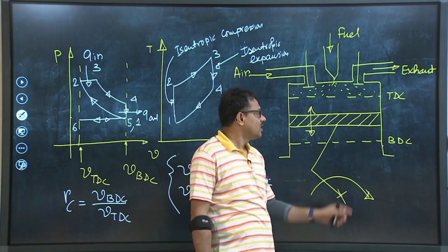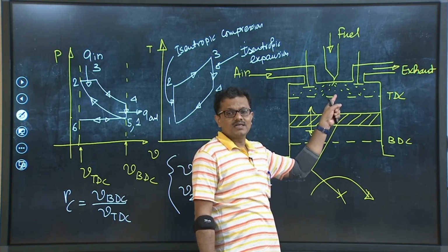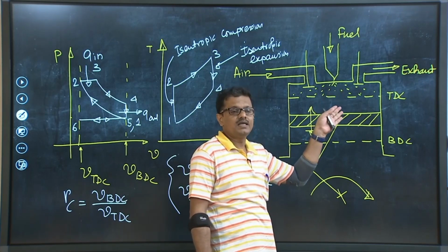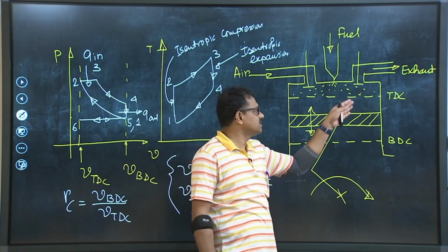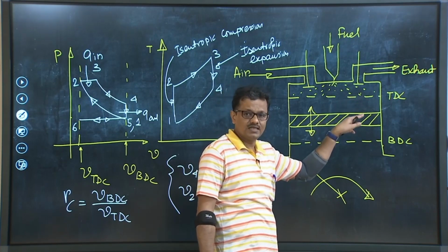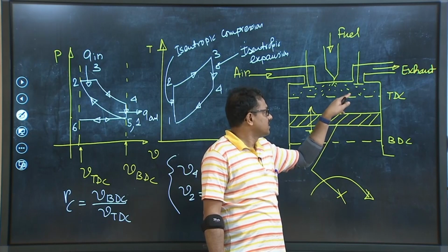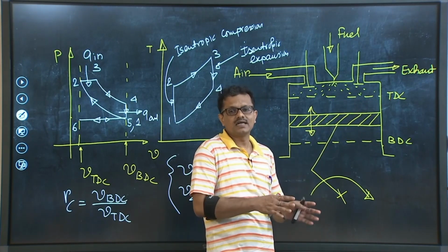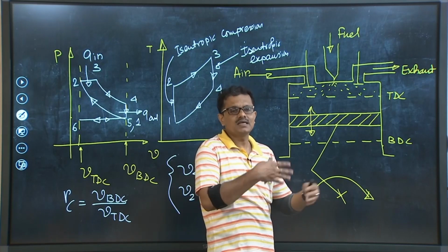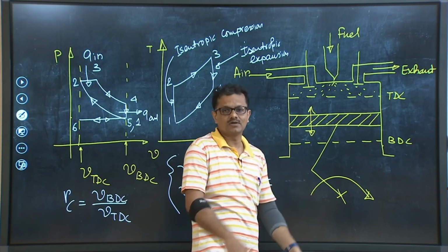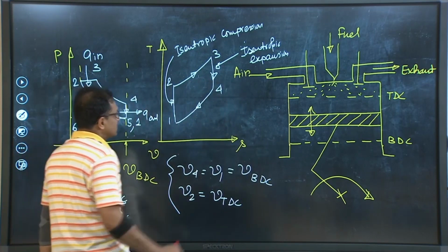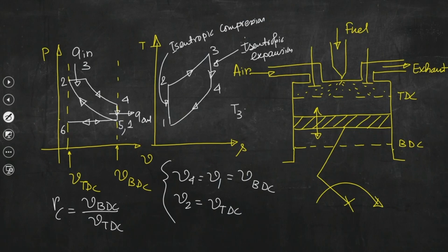and this is a very good assumption that I can tell you, because there will be a rise in pressure during the first phase of combustion, and that pressure perhaps will be reduced as the piston is travelling from TDC to BDC, but the rise in pressure due to the second phase of combustion will compensate that, and as if the pressure is remaining constant during the entire process of combustion, and that is represented by this, right. So, what we can see from here is that T3 equal to T max.